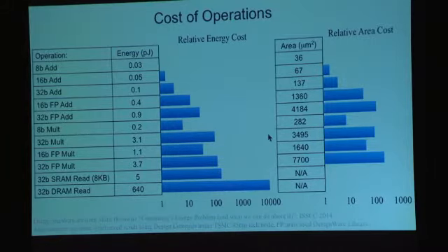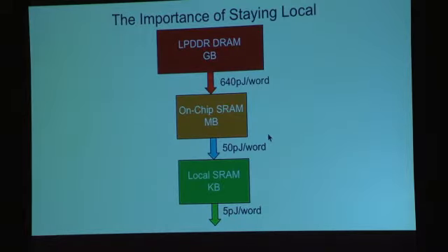It's also really important, when you're looking at the advantages of reducing precision, to be able to get a larger effective working set in a certain size memory. Because there's a huge advantage to capturing a working set at some level. If I can capture my working set in an SRAM that's right next to my arithmetic units, that's huge because fetching a 32-bit word out of local SRAM is only 5 picojoules.